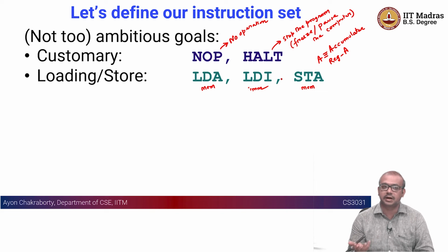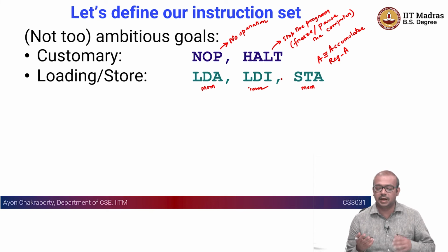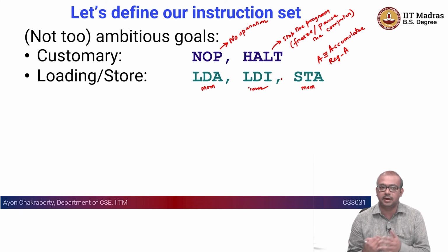So this is one restriction, one of the immediate shortcomings of our ISA that you can directly see. We have not put enough thought into creating this instruction set. Of course, it is going to have limitations. Although I have space in my accumulator, I can support up to 1 byte, I am only able to load a constant that is up to 15. That is one drawback.